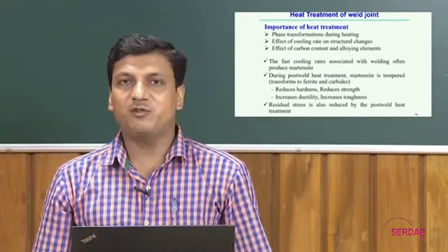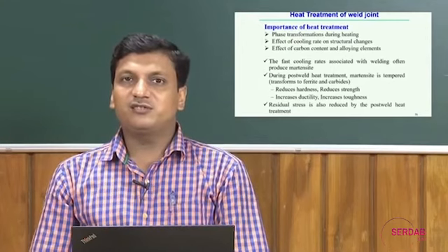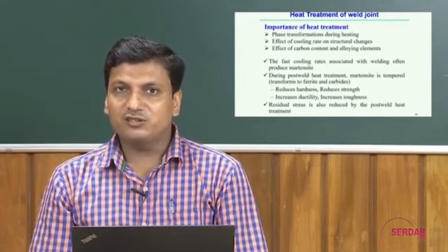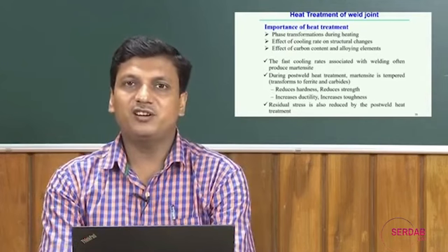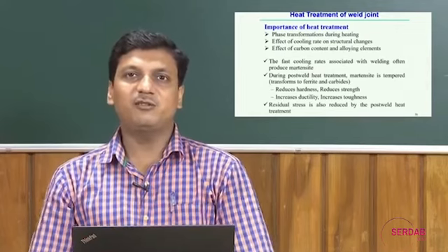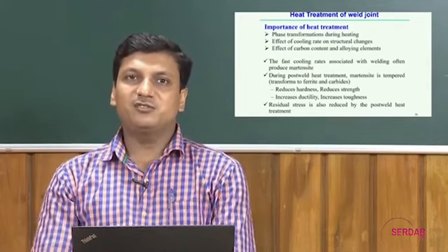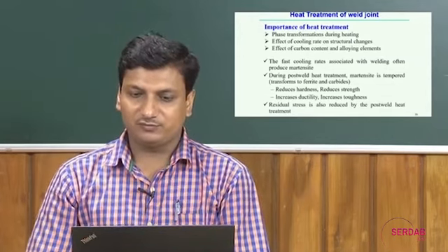Therefore, it is very important, looking into the structural changes, to decide whether heat treatment of the weld joint is required or not. Normally, if the material contains high alloying elements or the steel contains a high amount of carbon content, in that case heat treatment is very much essential to improve the weld joint strength.